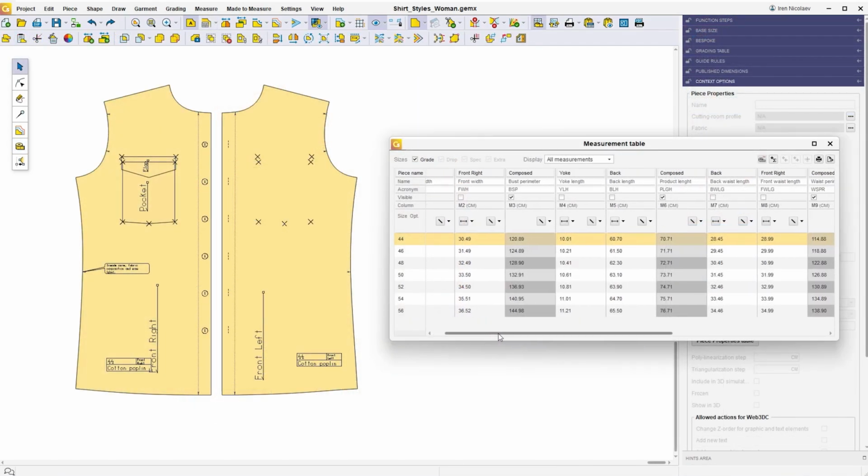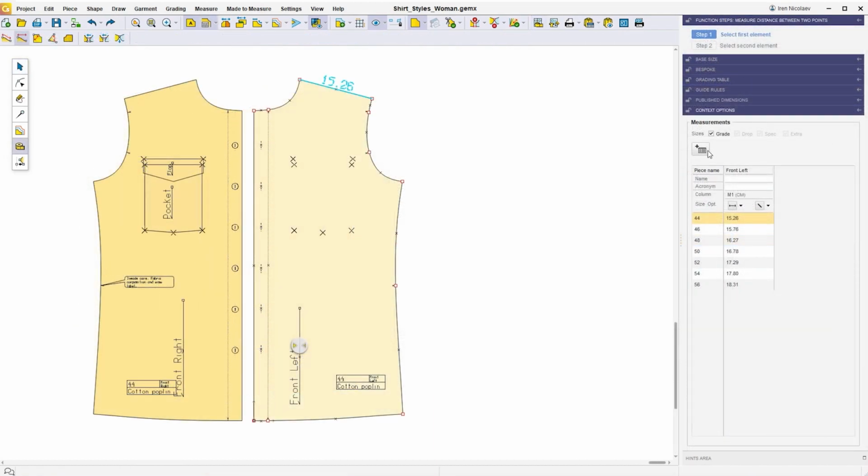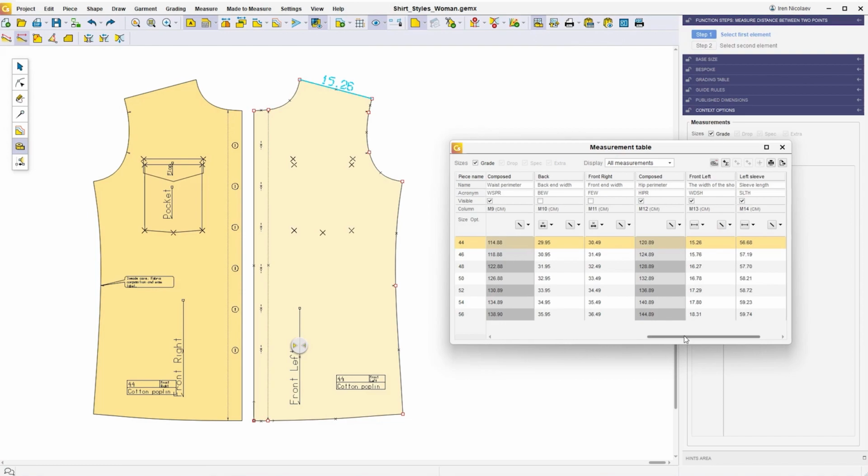Don't worry, you can save it and embed it permanently into your model. To do this, you should press the Save Measurement button. The measurement will be saved in the Measurements table, which is available in the Application General toolbar.